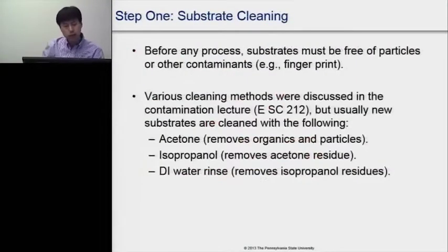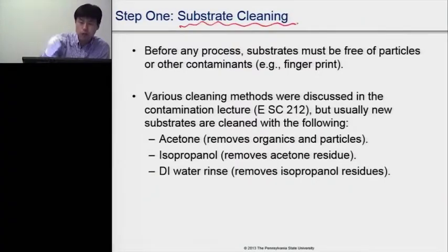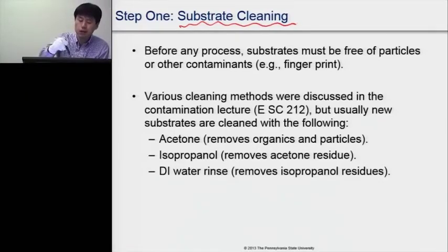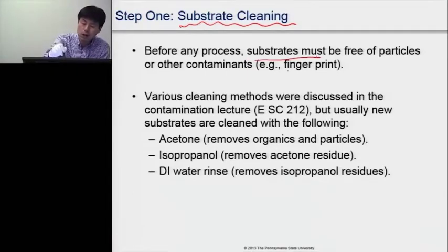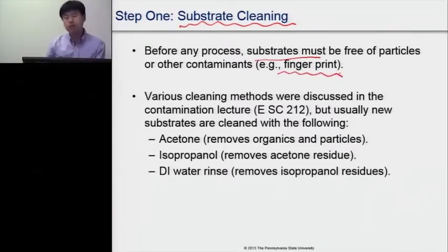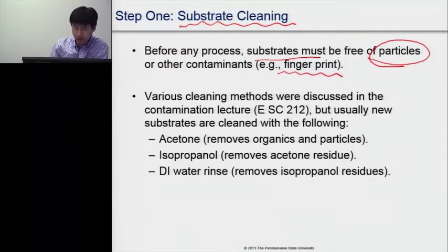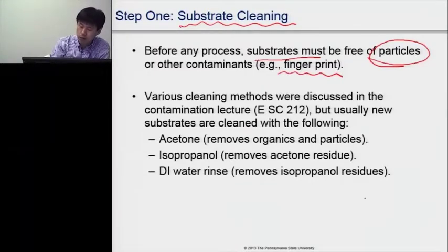So more details about these processes. In step 1, we will do the substrate cleaning. Before any process, the substrate must be very clean. It should be fingerprint free, and specifically particles cause serious problems, because we will spin coat the resist.